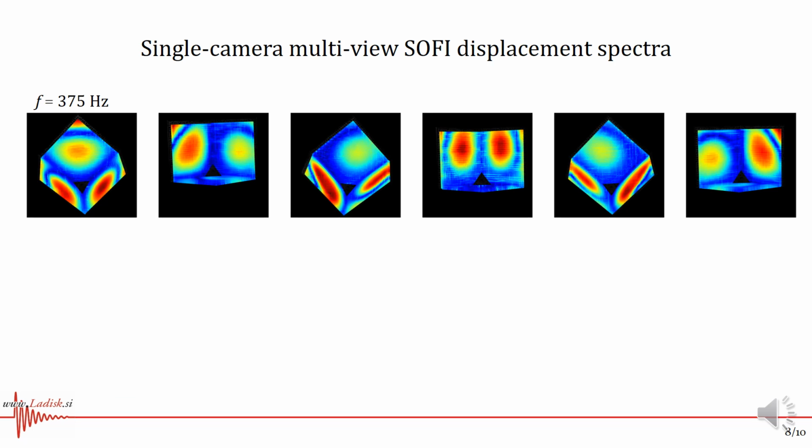Here we can see another deflection shape observed at a different measurement frequency. As spectral optical flow imaging readily produces frequency domain images of the deflection shape by performing the Fourier transform on the image sensor, the post-processing required to produce image-based vibration measurements is minimal compared to conventional approaches.